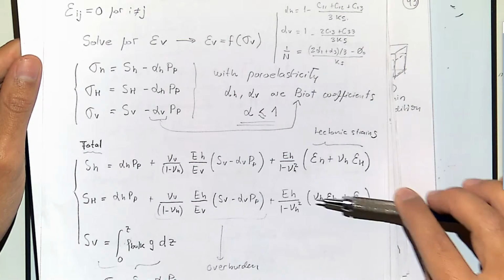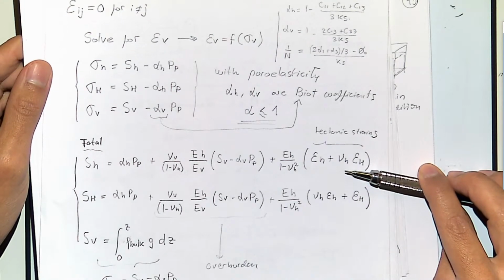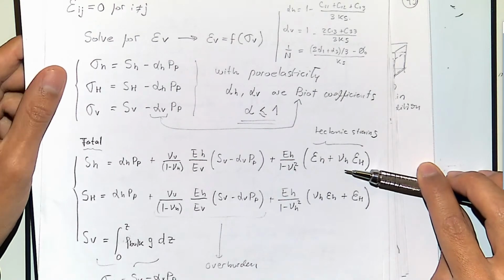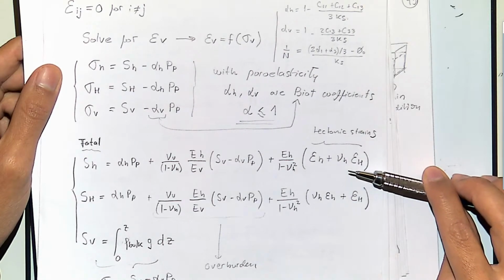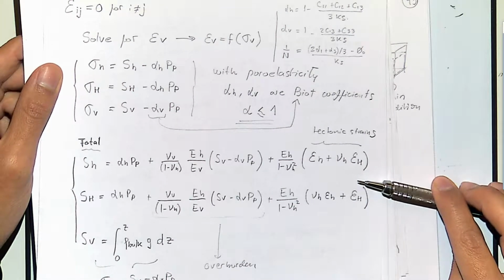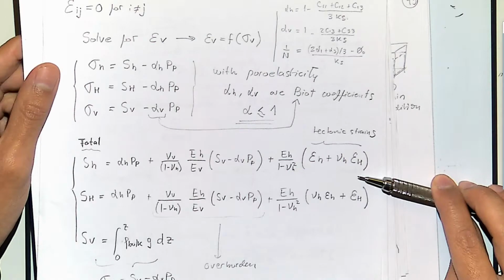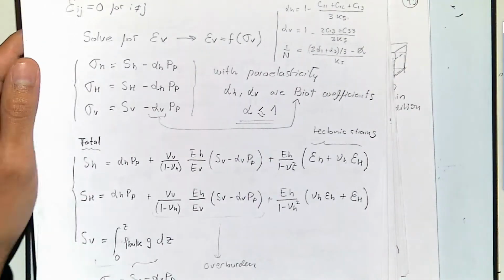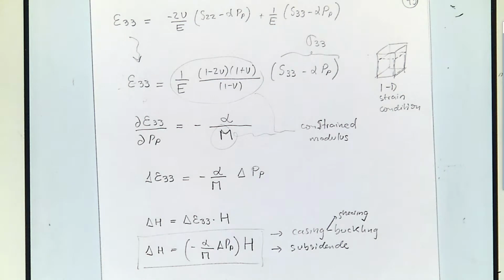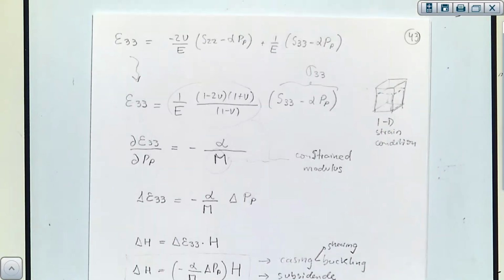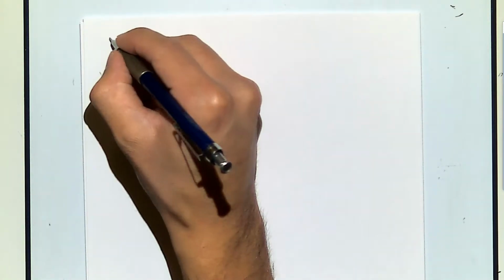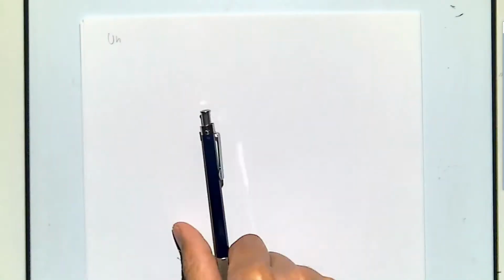And because this assumption assumes that, in some problems, particularly those related to overpressure, whenever the pressure is not hydrostatic, you may not apply this directly because the problem may be undrained, not drained. And these are drained equations. They are drained, yes. Otherwise, we'll have an additional term, which we're going to see now. Okay, so with this, we finish the drained part of poroelasticity, and now we're going to talk about undrained loading.